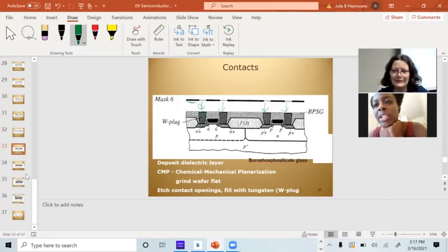What are the masks normally made of? The masks have to be made out of a material that will withstand being bombarded with tungsten at a high temperature and pressure without allowing the tungsten to go through. Is that why there's that titanium layer you saw in the slides? No, the titanium was for passivation. I don't know exactly what they use now, but it's got to be pretty sturdy stuff, because this is going to be coming in at maybe 800 degrees Celsius at a high pressure, and it's got to withstand that without allowing any atoms to go through.